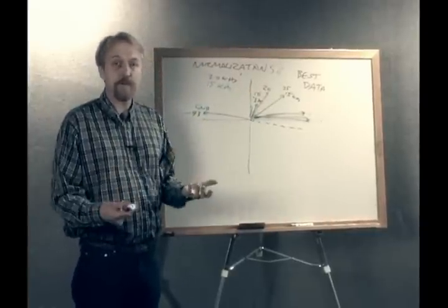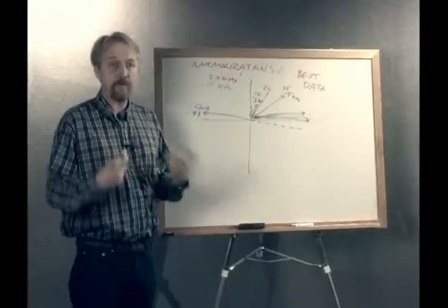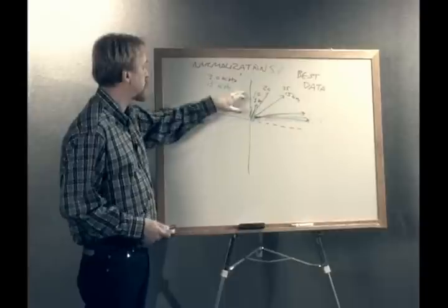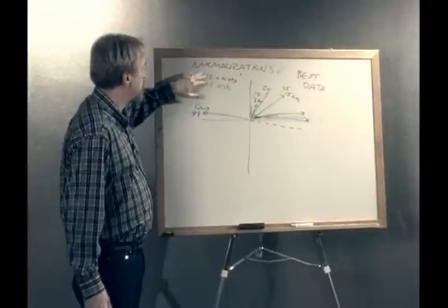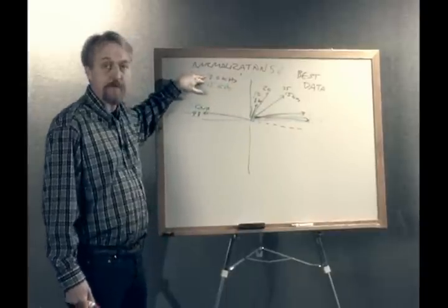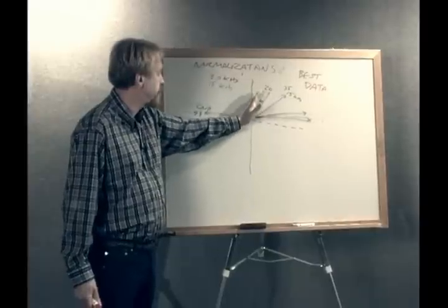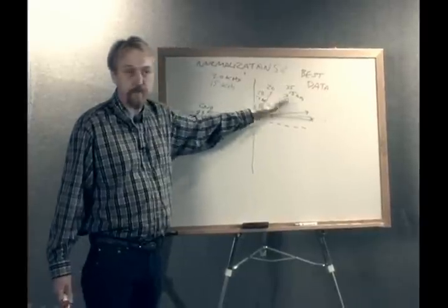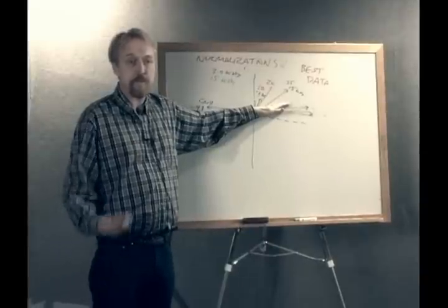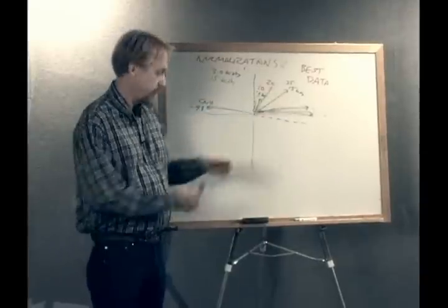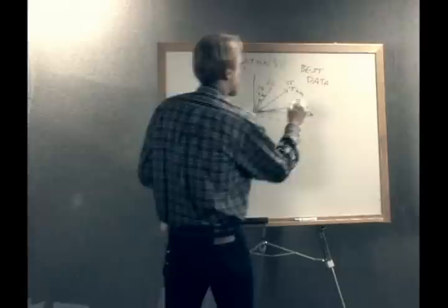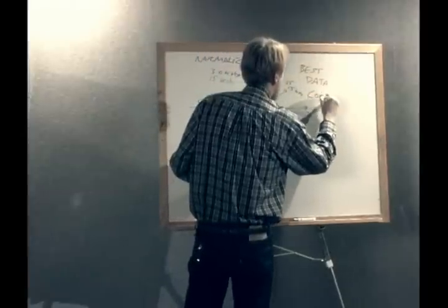And I'll report that to the operator on the screen in the form of a VDI number and an audio response. If, on the other hand, the results from these two operations don't agree, for example, if at one frequency I get a reading of 10 and at the other frequency I get a reading of 40, that reading will be suppressed. And again, we call this correlation.